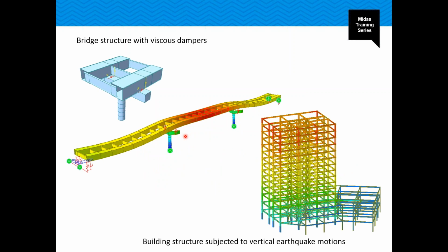Also, for a certain type of building structures, it is necessary to calculate the vertical dynamic response. In some cases, several hundred modes are necessary in order to obtain 90% mass participation in the vertical direction. These are other examples showing that using the eigenvector method is not so efficient in terms of computation time and computer storage requirements.